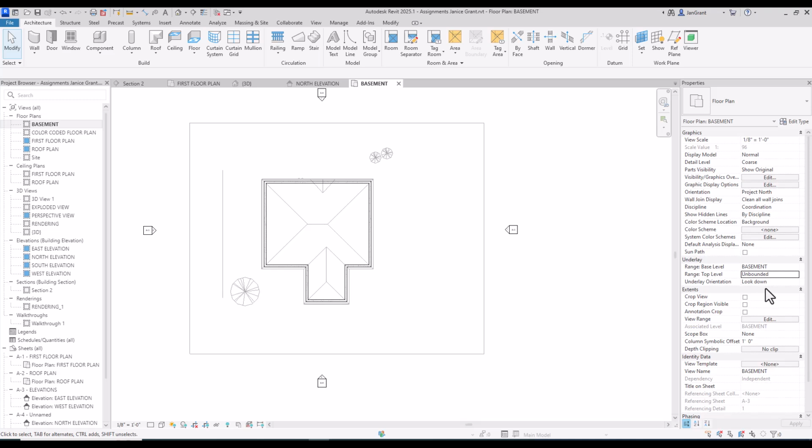it looks like even though I have the base level as basement, you would think that I could usually put first floor plan and pick apply, and then you would see the walls. But you see, I only see my table, which I've gone over and over, but I really still can't see my walls. I even looked at it in 3D with transparency and selected it.